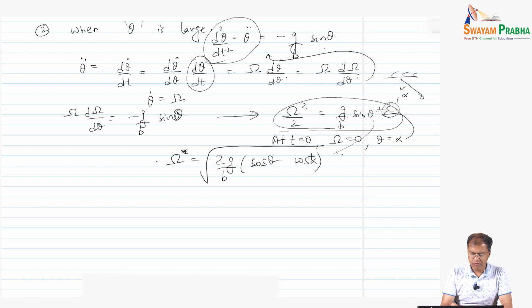We integrate this once more, so omega is d theta dt, and now we have this right hand side, and from here I can quickly find my total time t, after integrating, from theta from 0 to alpha. Notice the period is going to be given by the fact that the pendulum moves from alpha to 0 and then 0 to alpha again, and again back from alpha to 0 and 0 to alpha again. So there will be 4 such motions.